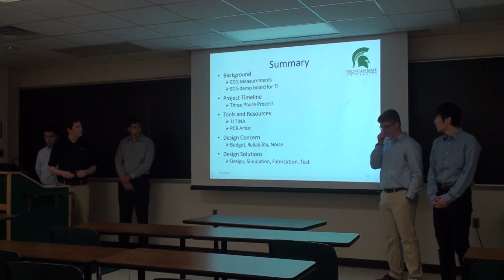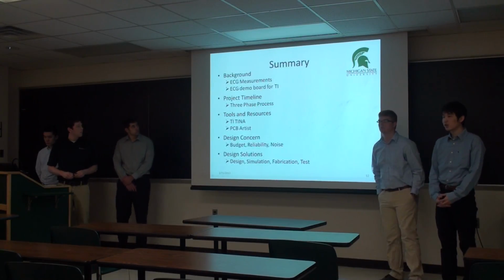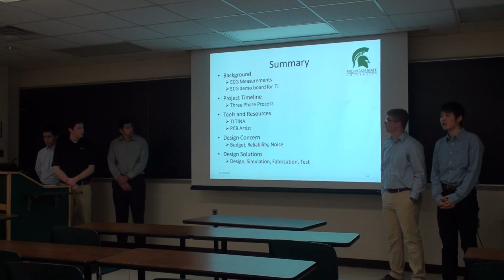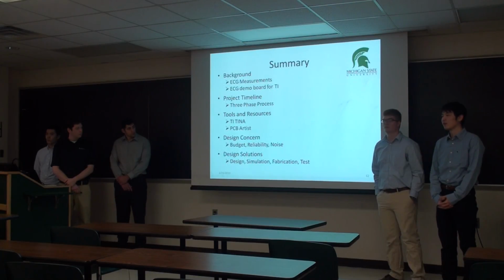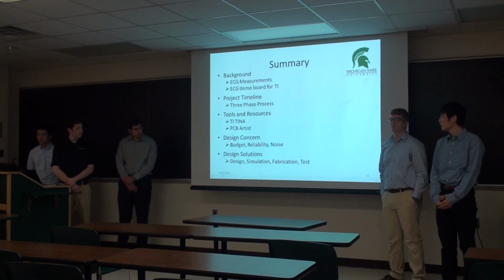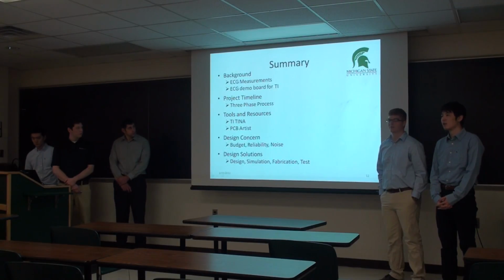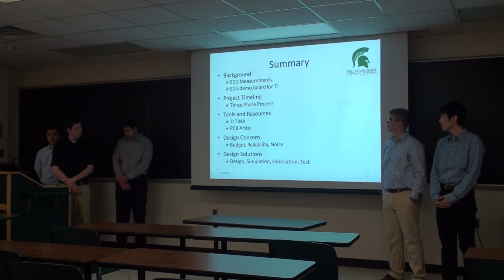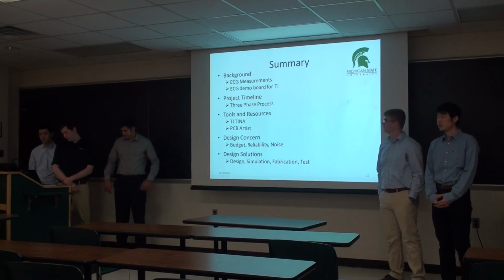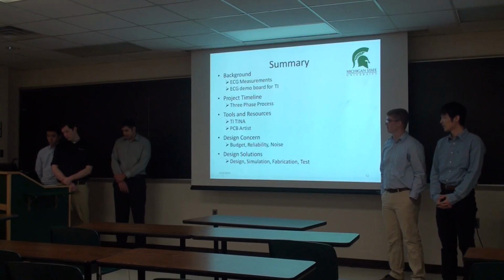To summarize, we have talked about the ECG signal, especially its purpose, the signal from the heart. Also, we talked about our project timeline. In phase 1, we got to design the analog front end. In phase 2, we're going to hook it up to the Stellaris microcontroller with the LEDs. In phase 3, maybe we can add on more features like the finger sensor or touching pad. Also, we talked about tools and the results. We use TINA now to do the simulation, and use PCB Artist to do the printed circuit board design.